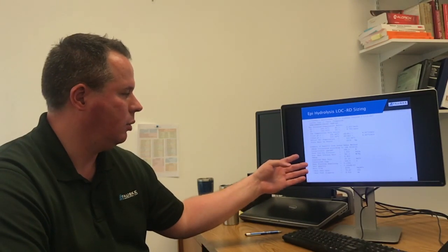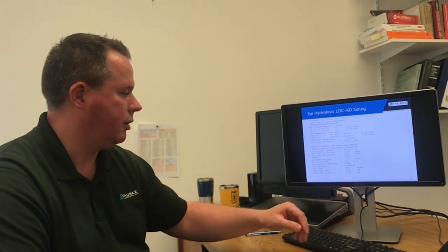And this shows you what your flow rates are and calculates that you need a rupture disc with a diameter of 9.8 centimeters. Now this is the ideal vent diameter, so it doesn't take the frictional losses into account. So when you do choose the rupture disc to actually install, you need to look at the frictional losses through the pipe.